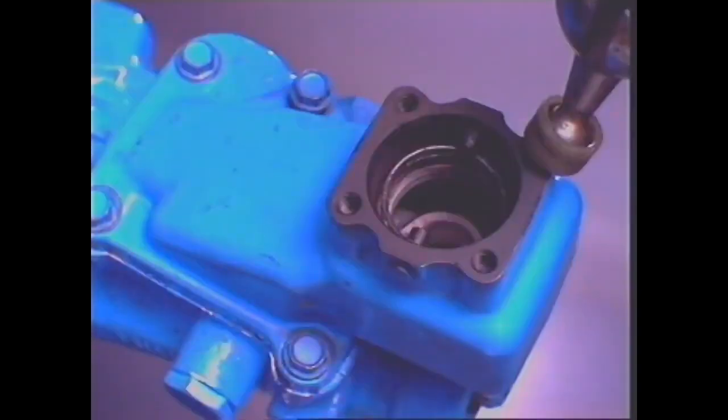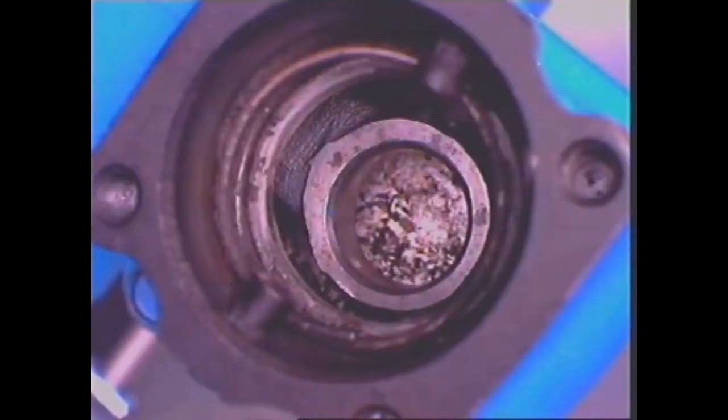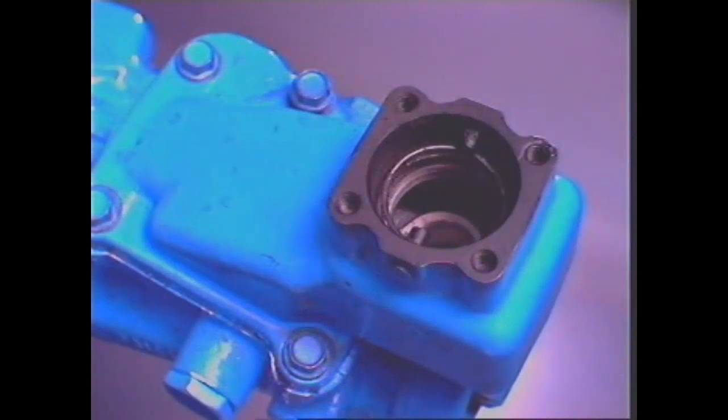In this design, the lower end of the gear lever fits into a socket in a control shaft inside the transmission extension housing. A short lever on the other end of the shaft is located in a selector gate, formed by slots in the 3 selector shift rails. They are supported in the casing and are moved backwards or forwards by the lever. One rail moves to engage first or second gear, another serves to engage third or fourth, and the other operates fifth or reverse.